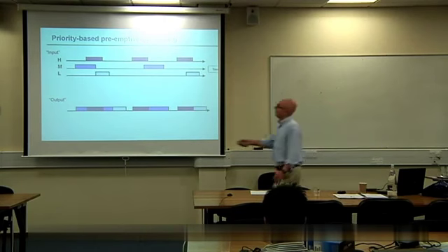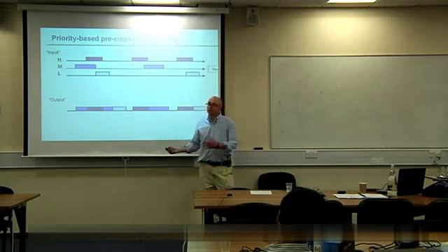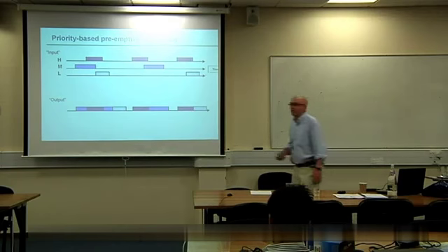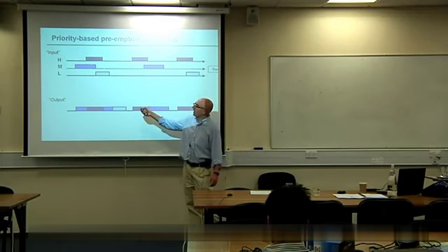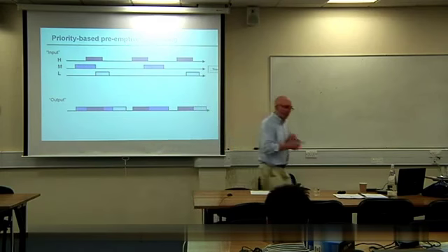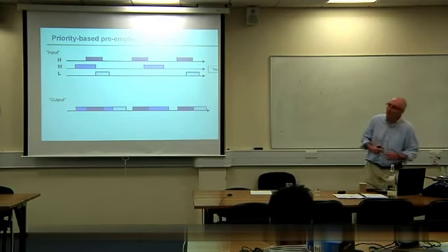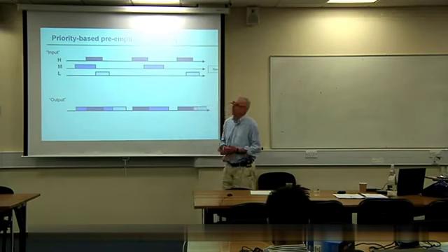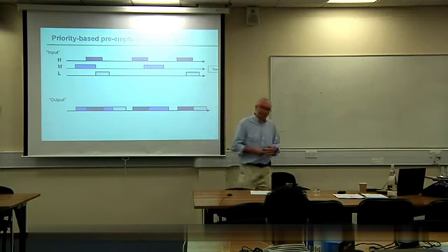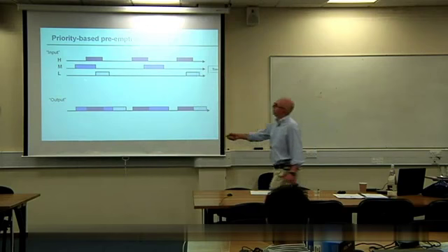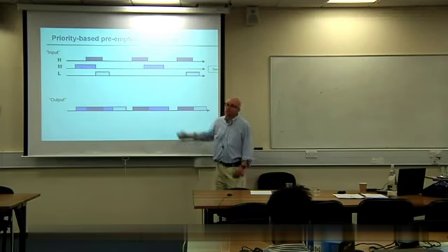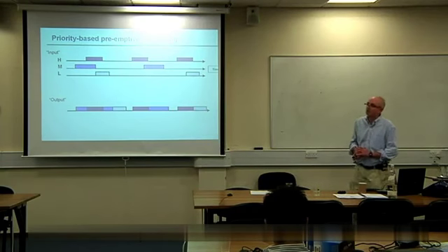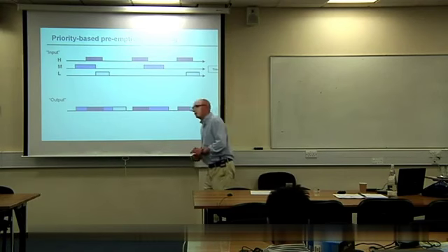Because what's happening here is the low priority task, because of the shared resources, is effectively being treated as if it has higher priority. Because it's using a resource down here, and because we can't deal with a situation where the resource is half used, when access to that resource is incomplete when another task interrupts, we have to let that resource access complete. Implicitly this task is being given, for some time, a higher priority than you've originally allocated to it. And it's an effect known as priority inversion.